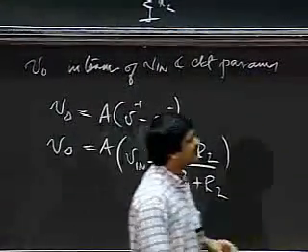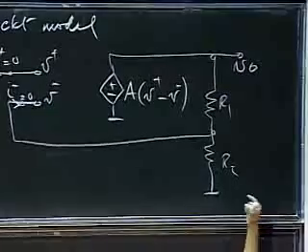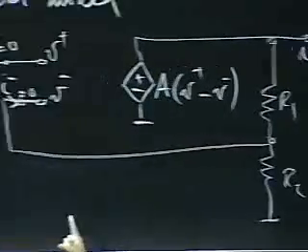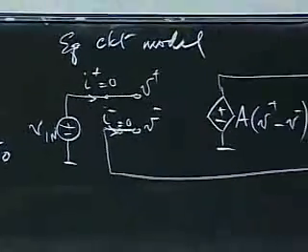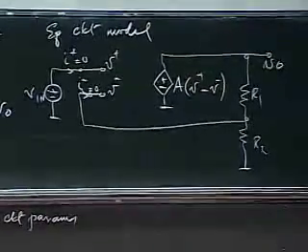Okay, let's stare at that for another second. The voltage at this node here is simply given by the resistive divider because no current is flowing in this direction. And no current flows in because I'm telling you there's no current there based on my abstraction. I'm telling you I minus is 0. So that voltage is simply the voltage at this resistive divider.